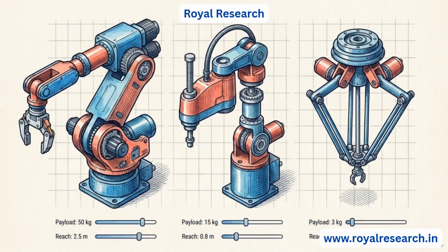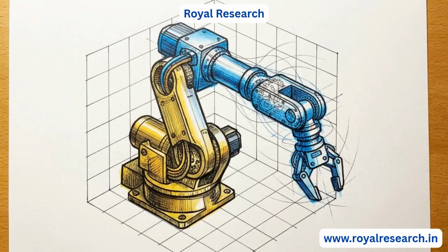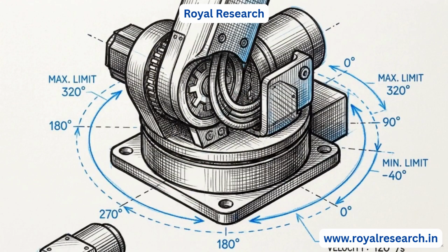Taking a moment to verify these specs now prevents the simulation from attempting movements that are physically impossible for the real-world machine. Next, we add the environment. You can drag and drop your workstation's CAD files, like a STEP or STL, directly into the 3D space. RoboDK automatically positions this imported environment relative to the robot space, creating the physical stage for the operation.